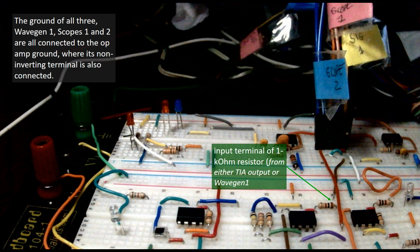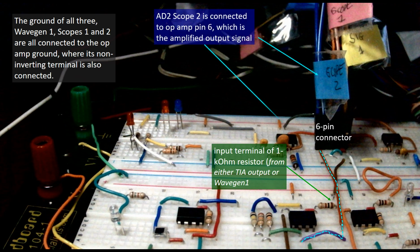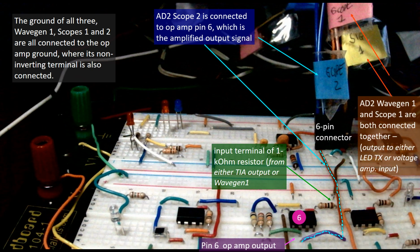A 6-pin connector is used as the interface between the AD2 and the breadboard. AD2 scope 2 cables are connected to the output of the optical receiver circuit, which is pin 6 of the voltage amplifier op-amp. AD2 signal generator waveGen 1 cables are connected to the test LED driver wires, and also to AD2 scope 1 cables, so that the LED driving signals can be monitored via scope 1, to be compared with the optical receiver output measured by scope channel 2.